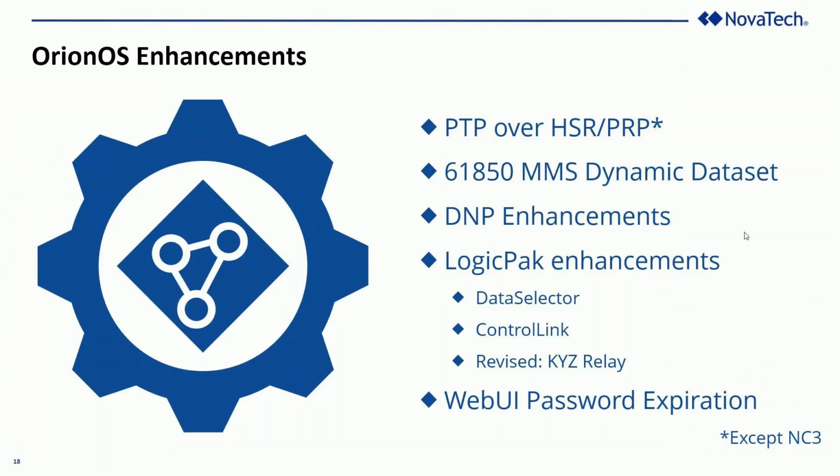So if you've got unsolicited servers out there that only send communications when something's wrong, and it might not send anything for 6 hours, 10 hours, might not send anything for 20 days, but you still want to know whether that communications channel is up and working, then you would use the request link status to make sure that you are still in communication with your unsolicited devices.